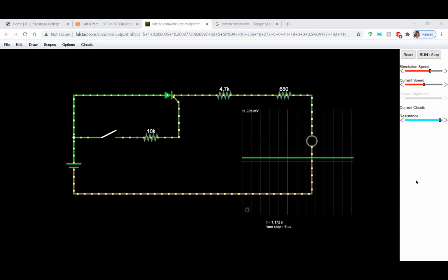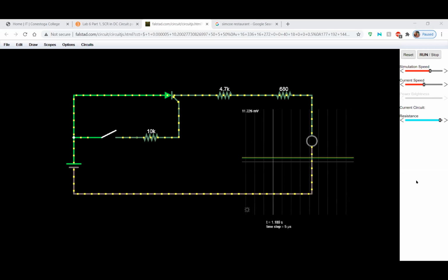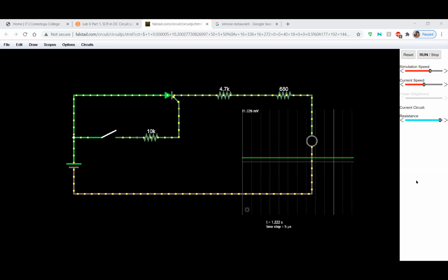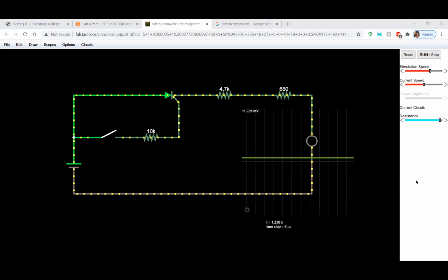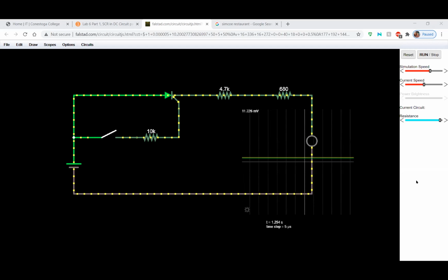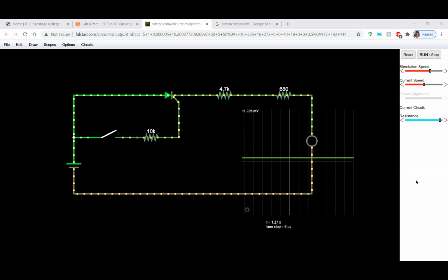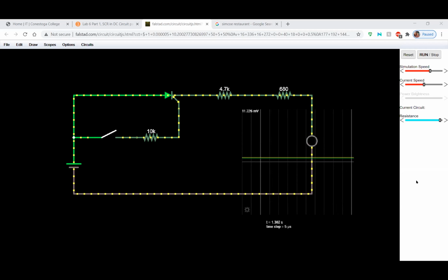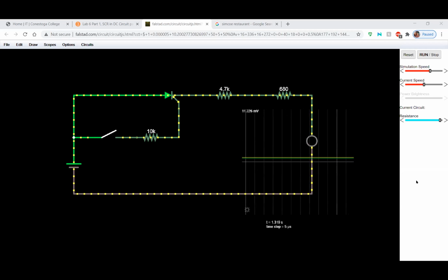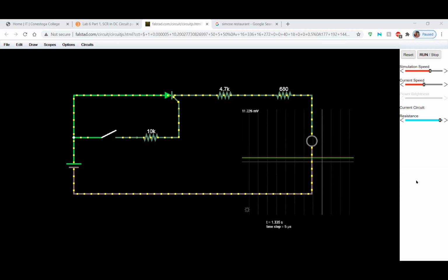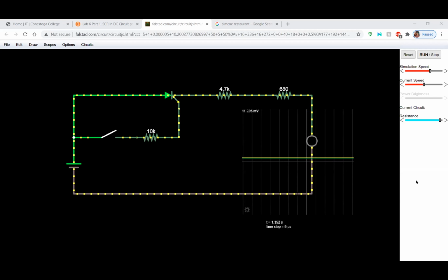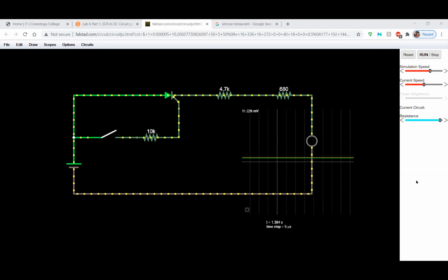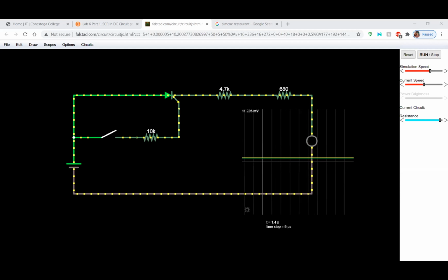Beautiful, Nate. Nate says that it's like a relay, and that is completely true. It's going to be behaving as a relay, with the advantage that a relay is mechanical. It is an electromechanical device. And how fast can you turn a relay on and off, right? Just a few times a second. While in the case of the SCR, it can be turned on and off thousands of times per second, which is a great, great advantage. But thank you so much for the comment.